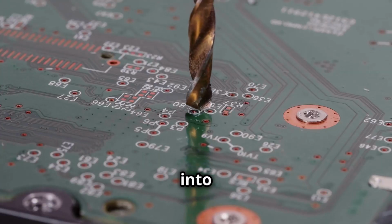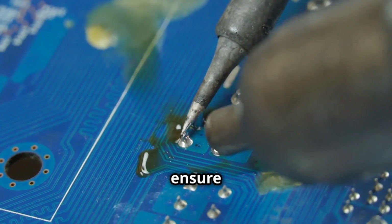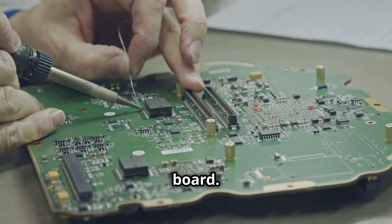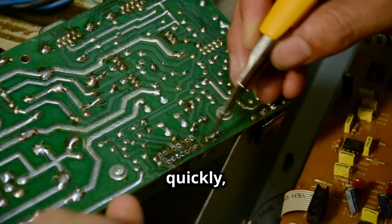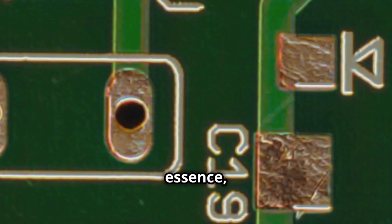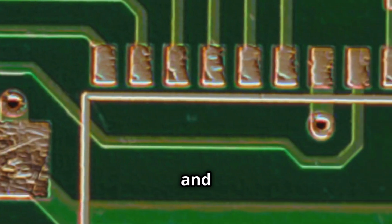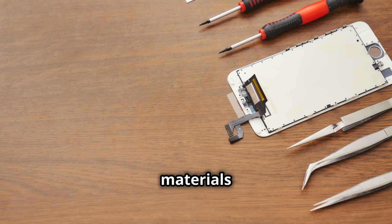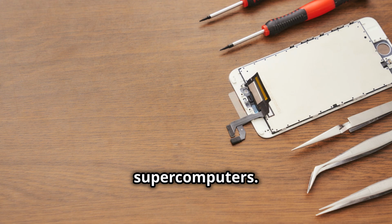Next, holes are drilled into the board for component placement. These holes are often plated with conductive materials to ensure a strong electrical connection. Finally, the components are soldered onto the board. Solder, a metal alloy, melts at a relatively low temperature and solidifies quickly, creating a secure bond between the components and the PCB. In essence, PCBs are a fascinating blend of conductive materials like copper and solder, and non-conductive materials like fiberglass and epoxy. This intricate dance of materials makes all our electronic gadgets possible, from smartphones to supercomputers.